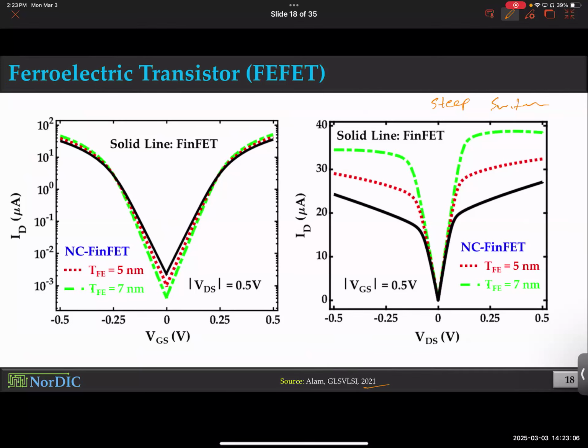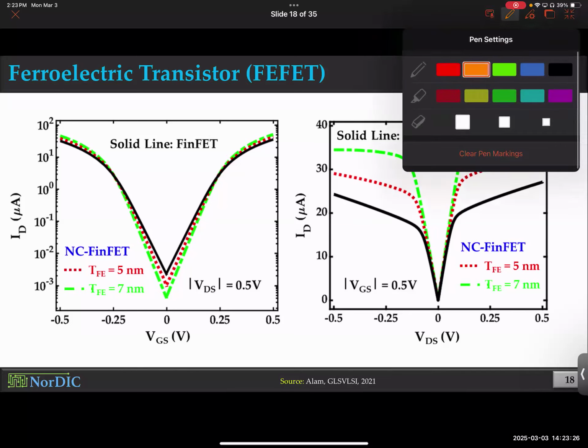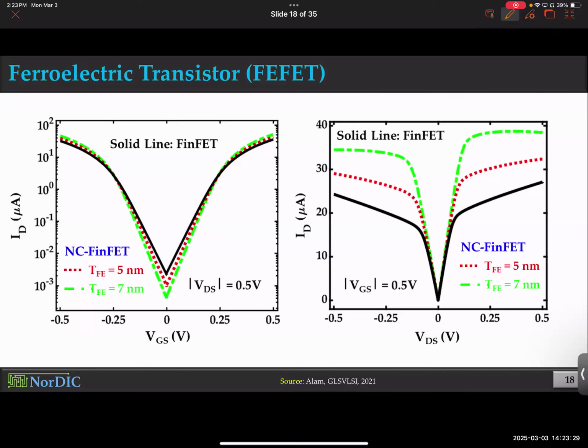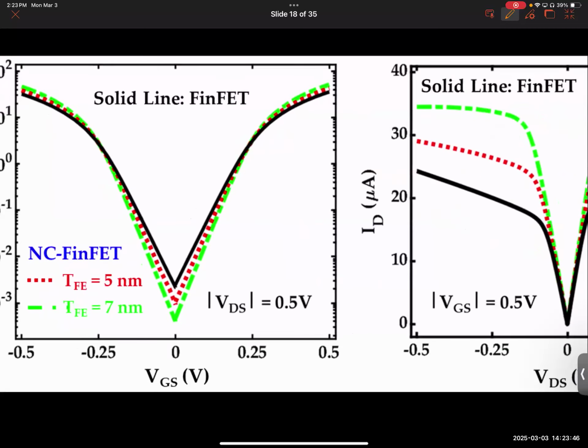There was a question about off current and on current and subthreshold slope. And we talked about how people are trying to solve a fundamental barrier, 60 millivolt per decade, which is known as the Boltzmann limit. And our transistors are limited to that. The way you break it would be to find interesting physical phenomena that will help you break that limit. And one way would be to use negative capacitance. I'm not explaining exactly how that helps in breaking that limit. Well, maybe you already know, I don't have to explain. So it creates an extra source of amplification, and thereby it overcomes the Boltzmann limit. Okay? And let me show you this from this data.